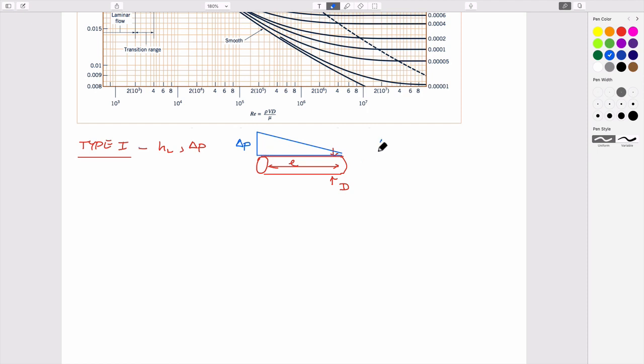And of course that pressure drop, delta P, is equal to head loss divided by unit weight in this geometry, right? So that's physically what it represents. Water comes through here at some velocity, which we have to prescribe. And I suppose we have material properties, which would be viscosity and density, which control behavior.